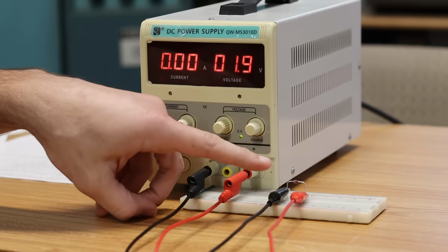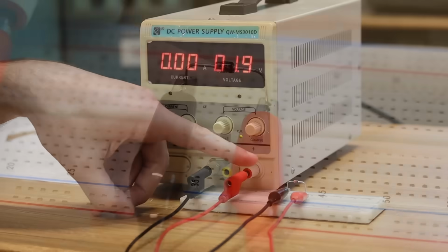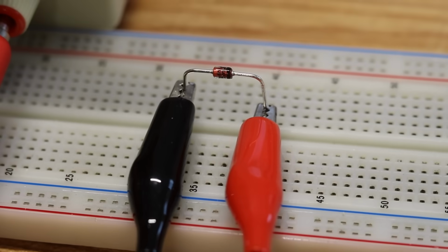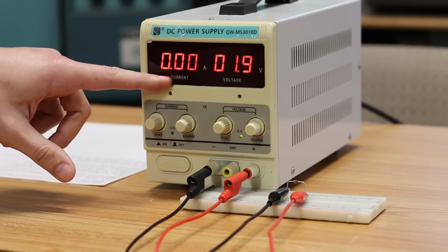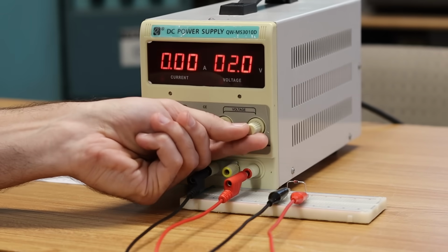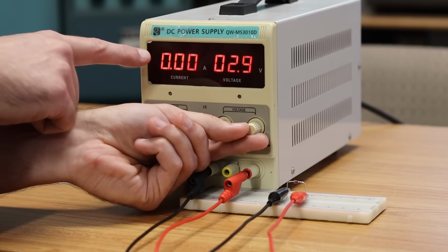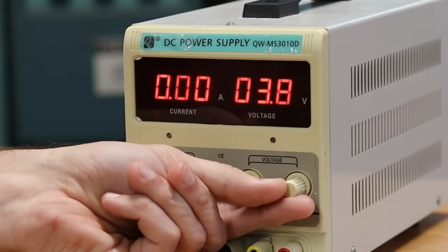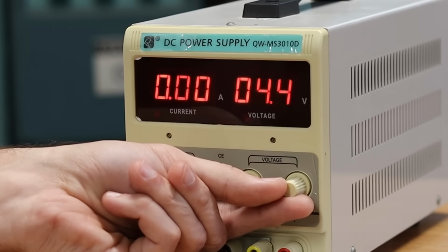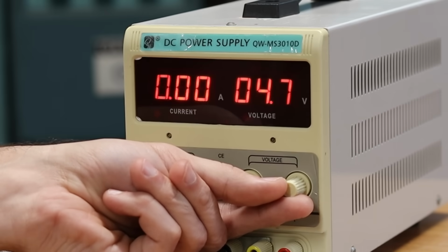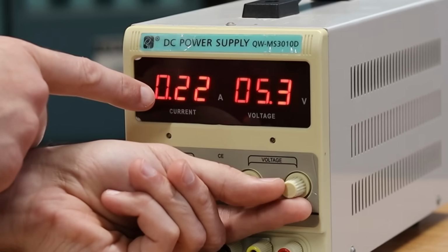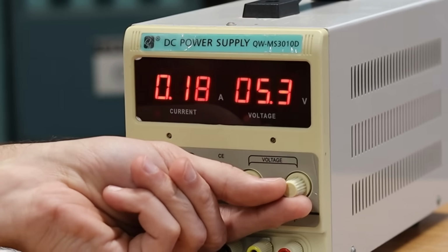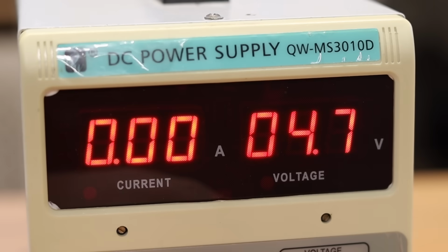I've got that little Zener diode hooked up to my bench power supply here, and I've got the positive hooked up to the cathode and the negative hooked up to the anode. And currently the power supply is at 1.9 volts and there is no current moving. And actually I can bring the voltage up and you can see that our current stays at 0.00 as the voltage rises. But once we get to 5.1 volts, where the Zener breakdown of this diode is, there it goes. You can see now we're starting to move 200 milliamps. And then we get below 5 volts and boom, our current goes right back down to 0.